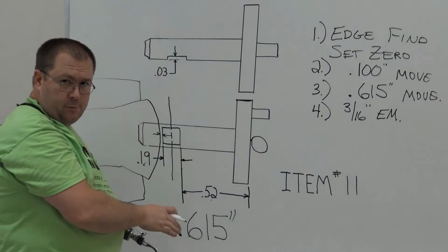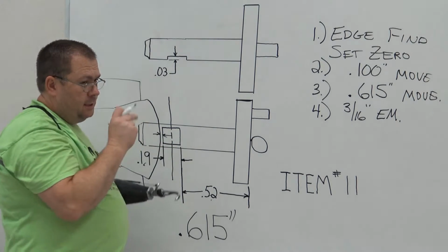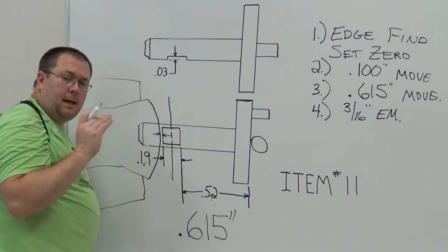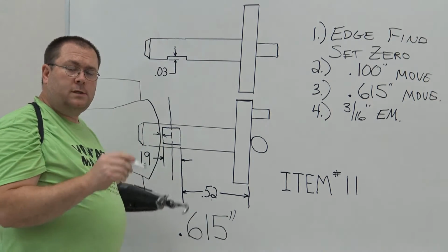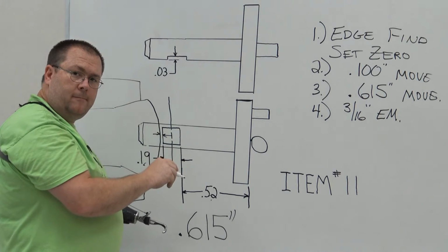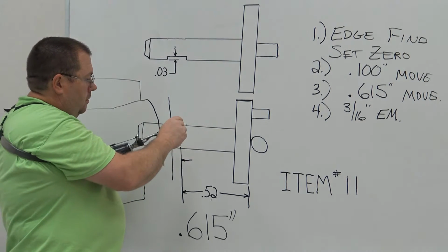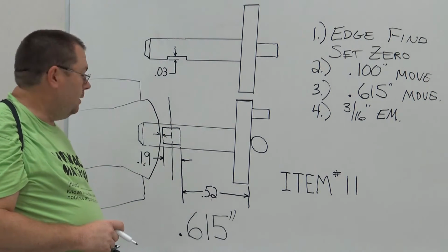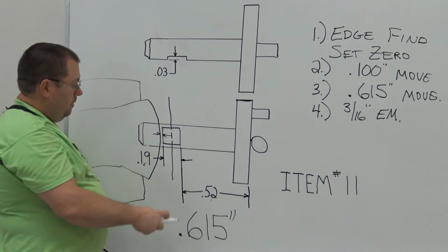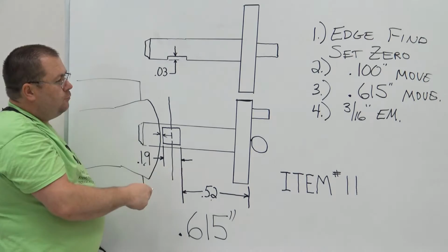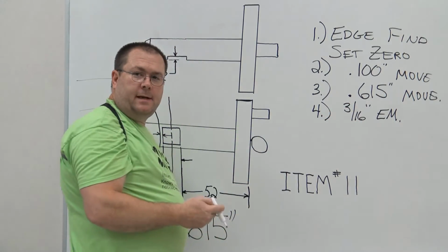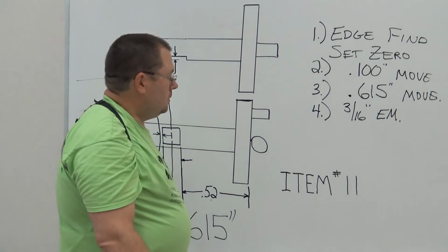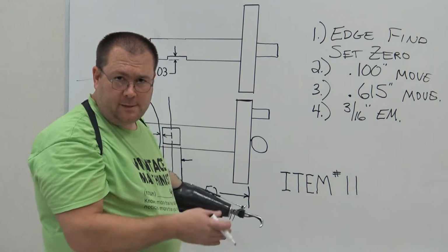4 times 100, which is our cutting speed. Well, actually, let me back up a second. This is actually tool steel, annealed tool steel. It's not mild steel anymore. It's 4 times the cutting speed of tool steel, which is 50. So it's 4 times 50, which is 200, divided by my diameter, right? And I'm going to round my diameter instead of 187 and a half to 0.2. It allows it to be easy for me to calculate. So 200 divided by 0.2 is 1,000 RPM.